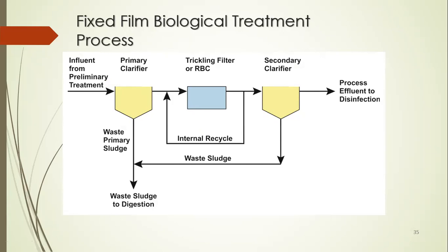attached to particles such as gravel and rock particles, and you create a filter-like medium, but at the same time around this filter material you will have growth of microorganisms as a slime layer, and the medium is stationary.